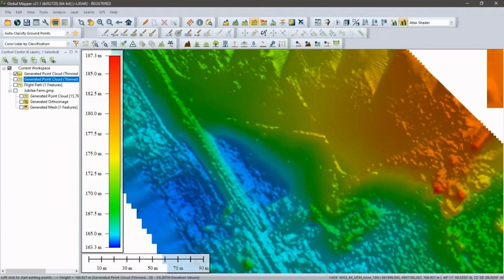Yeah, and in my to-do list, I was going to talk about contouring. I'm actually going to defer that now. If you're interested in what we can do with this DTM, I'm going to suggest you stop back for our terrain analysis session in a few weeks, and we'll talk about contouring, profiling, volume calculation, all the things that we can do with this data. Ultimately, with our pixels to point workflow, we've achieved what we needed to achieve, which is processing the images, identifying the three-dimensional characteristics of our area, and then generating our DEM and our DTM specifically.